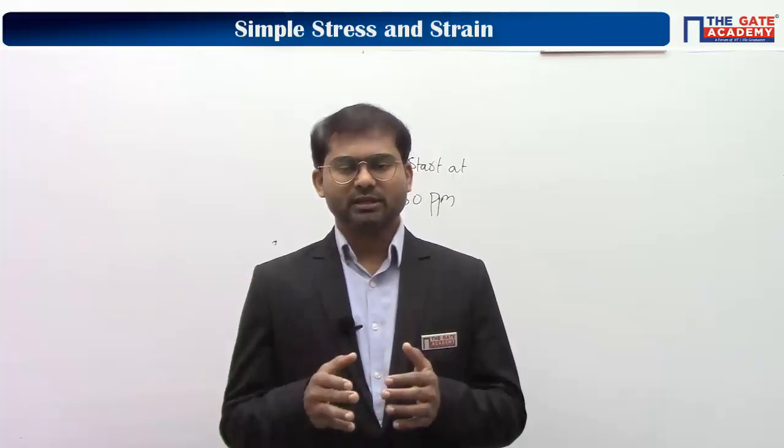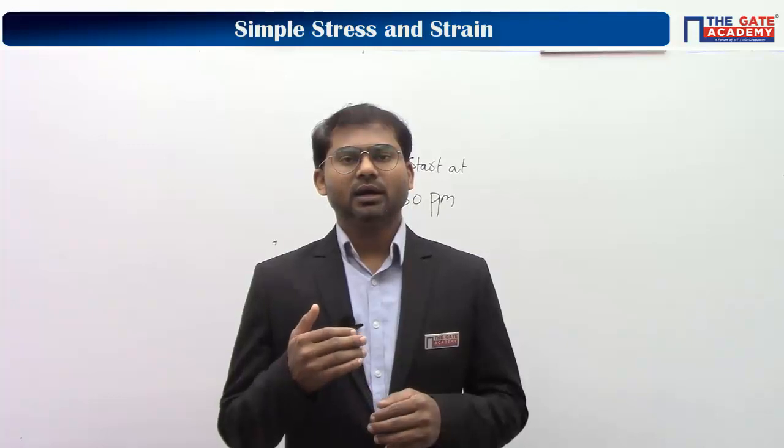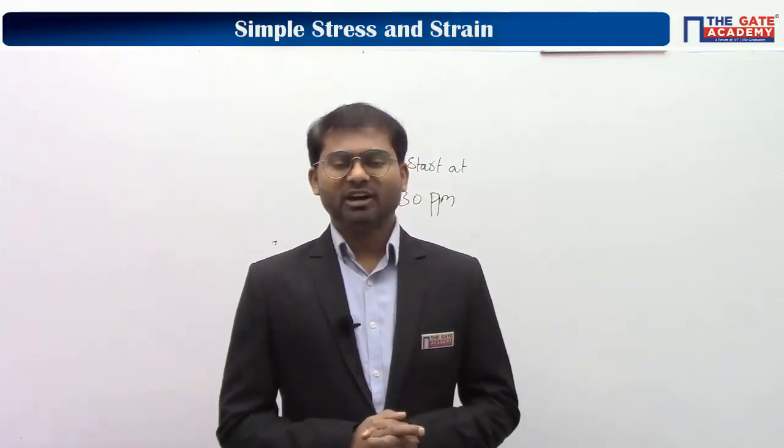So we should be keeping in mind that though ductile materials won't experience fracture at the phenomenon of yielding, still we discard them and take that failure has happened. So we should be very careful. Only in brittle materials we will wait till fracture to happen.